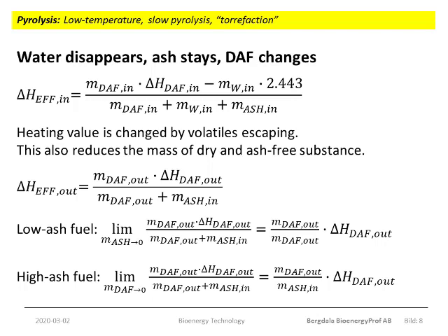But what does happen is that light hydrocarbon gas, volatiles of mainly low molecular weight, will form and leave the material. These light hydrocarbons will generally have high heating values, say 35 to 40 megajoules per kilo. But they will be diluted with other gases such as ammonia, acetic acid and such, which are also formed so as to reduce the mean heating value of the gases given off to maybe 15 to 25 megajoules per kilo.